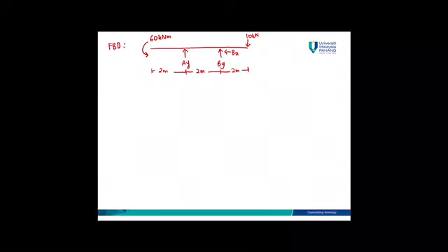From the free body diagram, you can see that you have 3 unknowns, which are AY, BY and also BX. If you have 3 unknowns, then you need to use 3 equilibrium equations. If you have 2 unknowns, then you need to use 2 equilibrium equations, and if you have only 1 unknown, you need to use only 1 equilibrium equation. So always start with summation of moment because you want to cut down the unknowns.